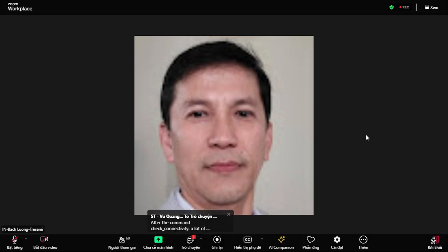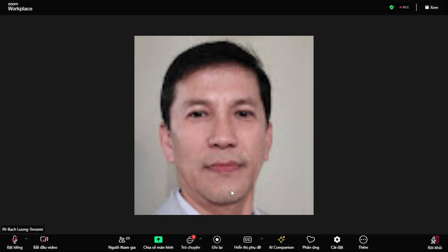How to fix hold time when finished routing? Okay, the same way, remember, you do opt design dash post route. The opt underscore design can have dash pre CTS, dash CTS, or dash post route. Let me show you.